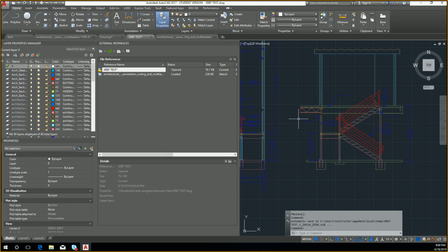I think one more. No, I just want to keep it. Okay, now go type P. So bring up your purge list. So expand blocks. See how it's there? Because you've exploded all of them, you're allowed to purge away that block. So for purge now, purge this item, purge all, that's fine. So hit close.